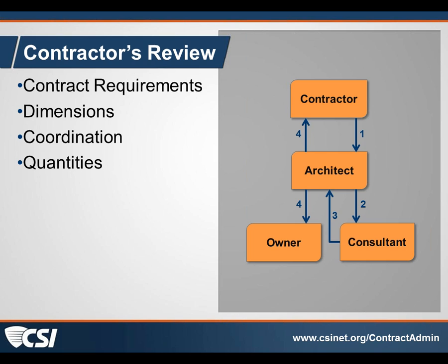Kevin O'Brien points out that both the AIA general conditions and the EJCDC documents require the contractor to field verify dimensions and quantities prior to submitting the shop drawings or other submittals to the architect for his review.